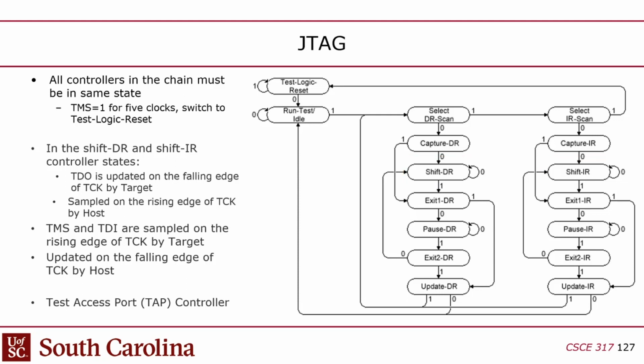Yeah, because you can get a generic JTAG master and plug any device into it and probe it. You can actually do a scan, and you can scan all the registers and figure out which devices are connected. In fact, I think you've taken 611, so you know that when you plug the FPGA in and you go in the programmer and connect it to the board, it already knows what FPGA is on there. It does that because there's a special instruction that identifies the device. So it reads that identification code out, and then it looks in a table and says, oh, that's the Cyclone 4E FPGA. It can get all that just by reading the JTAG. You don't have to tell it. It can glean all that from the JTAG transactions.